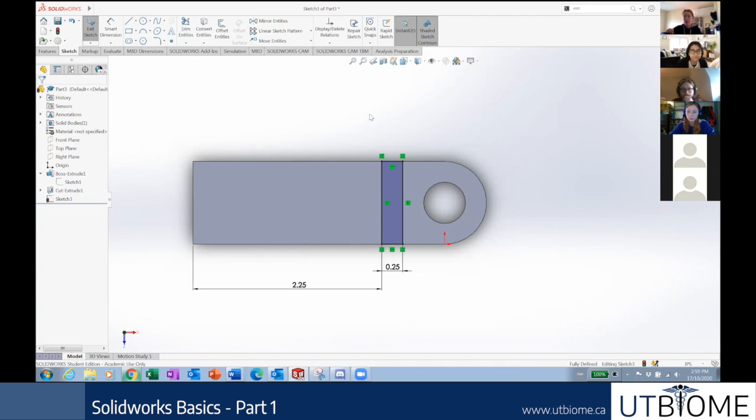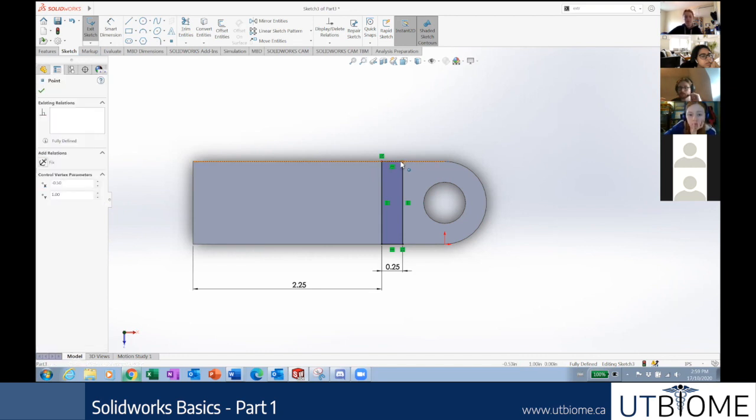Okay. Let me think. That's totally fine. That's 100% fine. The reason that still works out is, say here, I could even delete this one and delete this one down here. The reason it works is because we've said this point right here has to be on this line, and this point right here has to always be horizontal to this point. As a result, they will always still be on the same line. I realize it's a little confusing, but you don't need all those coincident relationships for it to make sense. If that kind of makes sense. Yeah. Thank you. Okay, no worries.